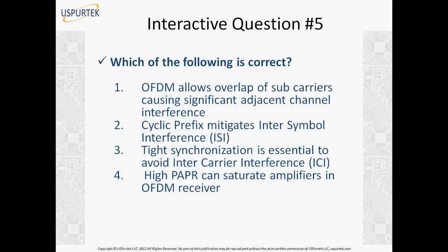This is a calculation of the sample data rate in case of the 802.11 standard. So let's take an example here. Let's say we use 64QAM. That means 2 exponent 6 states, or 6 bits. Code rate we are using is 3/4, and the symbol rate as per the standard is 250k symbols per second. Number of data subcarriers is 48.